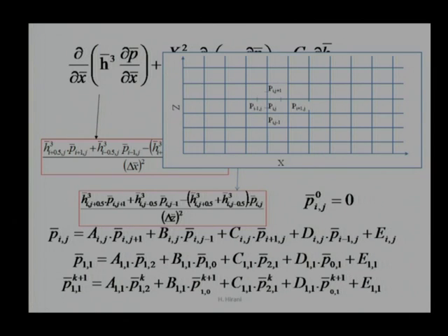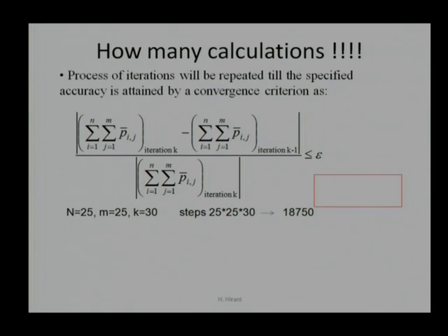We have not iterated anything, it is just the beginning. So, at the 0th iteration, pressures are known, and that is equal to 0. Now, we can start putting in all the 0s, and this equation will give us the value of pressure at node 1 for the first iteration. So, that will give a sequence, and that will give good results to us.